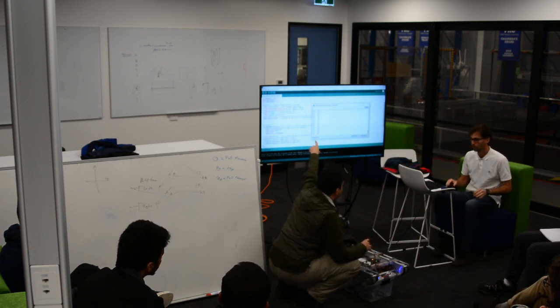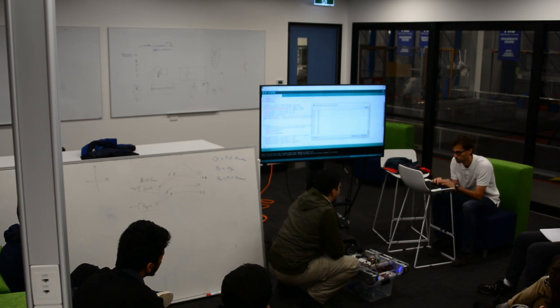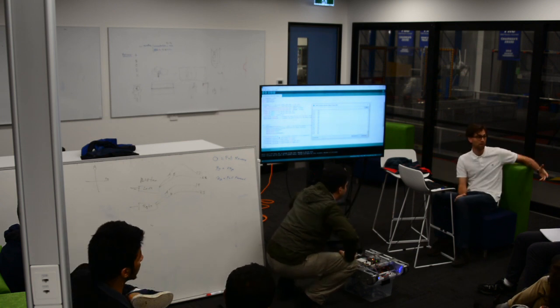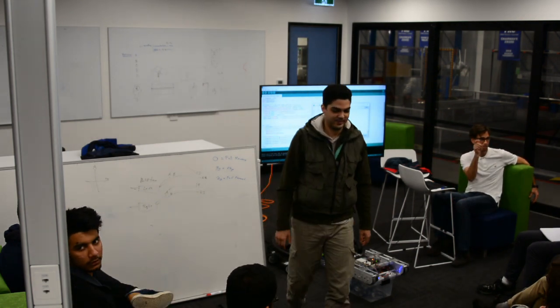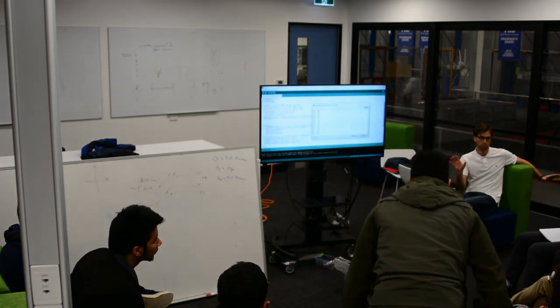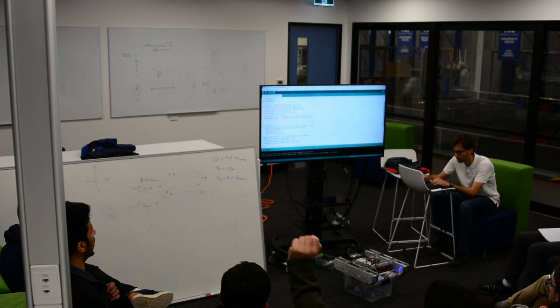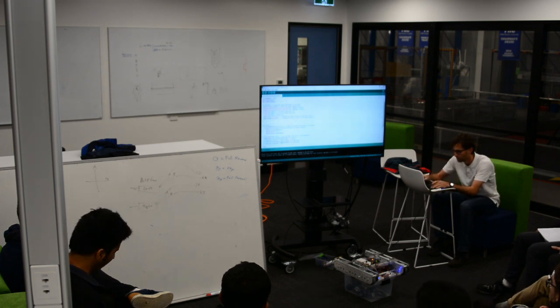Yeah, you were going to say? So if it's within, like, 10 of, okay, between 990 and 1,010, just leave it? Yeah, so that's called bang-bang with a dead band, or on-off control with a dead band. So you create a band where you stop, right? And so we could do that, right? How would we do that?